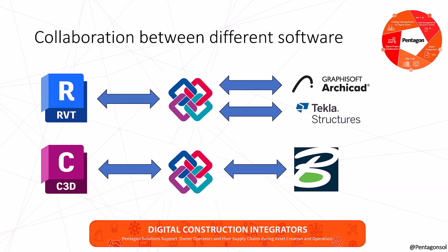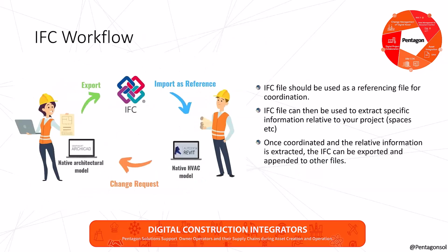This leads me on now to look at different types of IFC workflows. Again, IFC workflows will be dependent on software. However, as a generalization, it does look something like this. The IFC file should be used as a referencing file for coordination, both for graphical and non-graphical. The IFC file then can be used to extract specific information relative to your project. Again, in this example, likes of an MEP user having to use spatial information with an AutoCAD user.